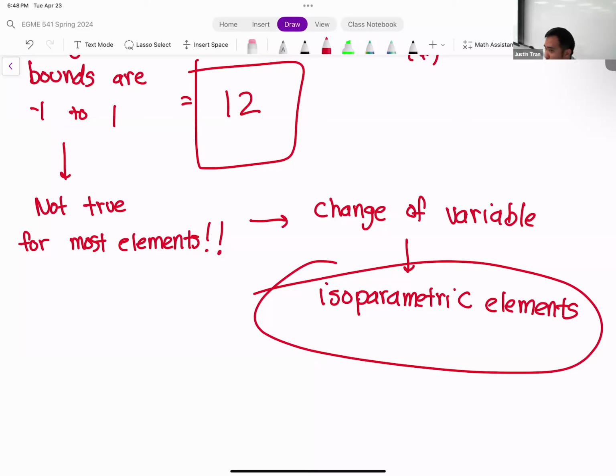Now you may have to multiply depending on your exact formulation. If you're doing an unsteady problem, you probably multiplied it by delta T, and probably by delta X squared, something like that. You have to account for those terms as well. So when you insert it into the right-hand side vector, you may have to multiply it by delta T or delta X or delta X squared, just to keep it consistent with the rest of the equation.